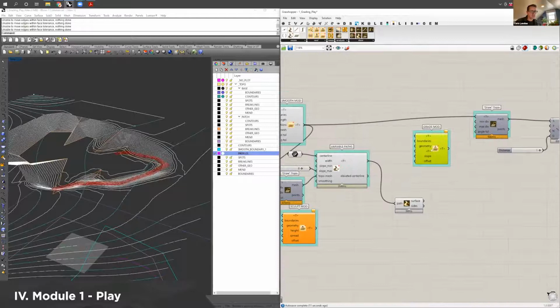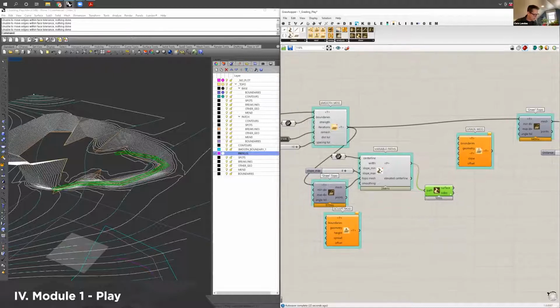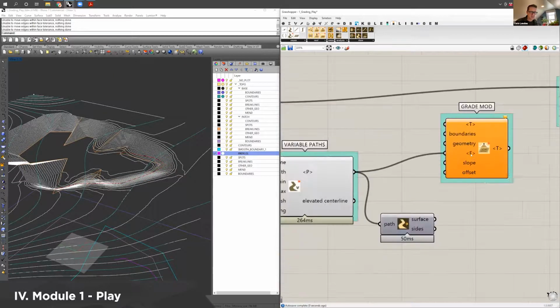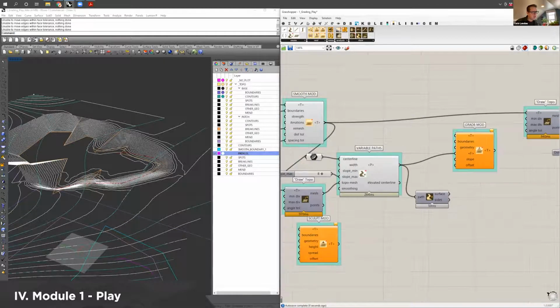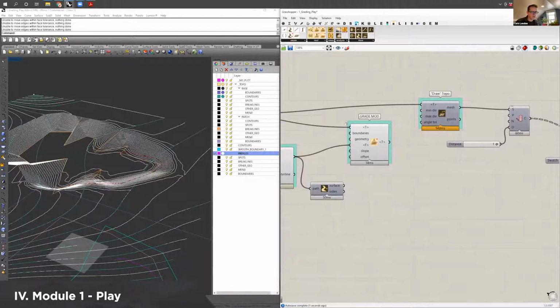And I can simply input the path. I can input either the surface or the path, which is kind of nice because you don't necessarily have to draw it. So we can hide this, Control Q. I'll put this right into the features input, the F there, and then I'll plug my terrain from the step before into here, and I'll draw this terrain. And it's going to look weird, and I'll explain why.